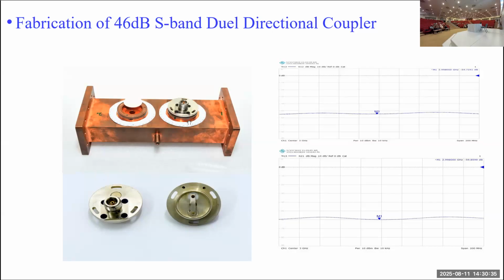What is the coupling? If it is 50 dB, it means if you say 10 raised to power 5 volt per meter electric field gradient inside your waveguide, your intensity of electric field in volts per meter is 10 raised to power 5, then only 1 volt will be coupled to the antenna. And this coupling you measure on your oscilloscope or on your power meter allows you to back calculate how much power is going in.